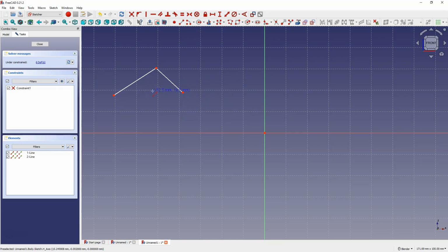However, drawing shapes consisting of several lines in this way is not entirely convenient, and a better method may be to use the polyline command. I will delete this geometry. OK, I select the geometry and press delete key on the keyboard. Now select the create polyline command, and with this command we can draw a shape consisting of several lines. Okay, I'll delete this geometry and let's again select create polyline,